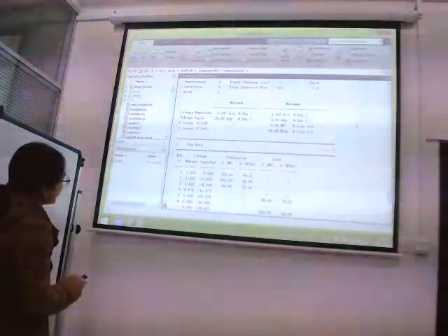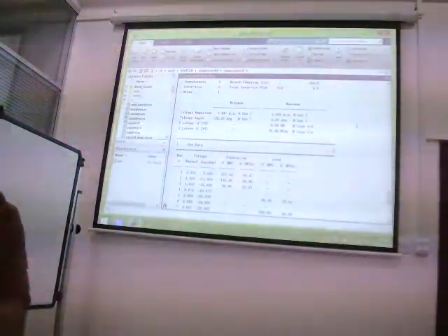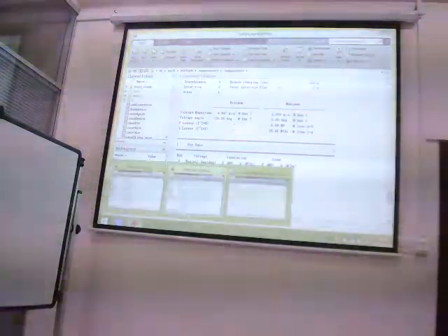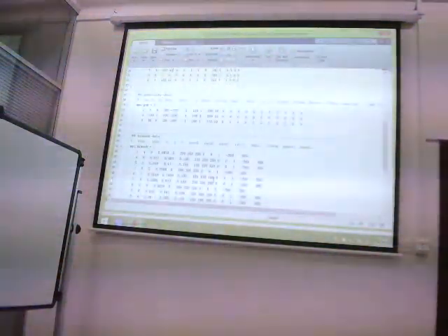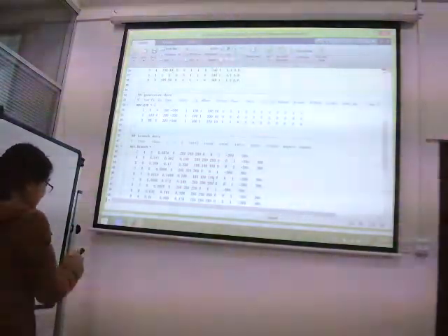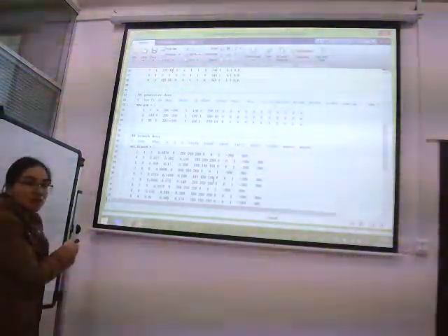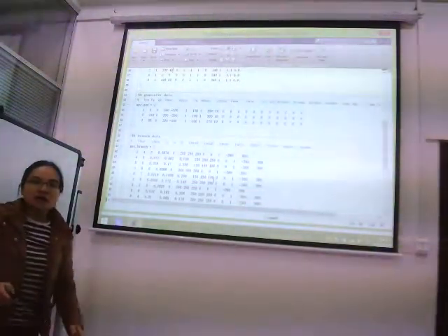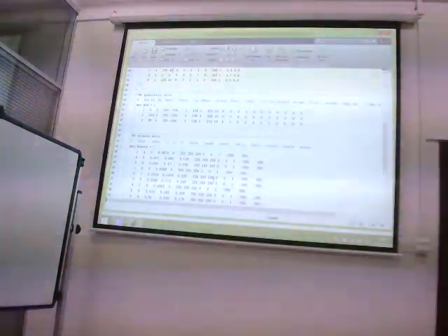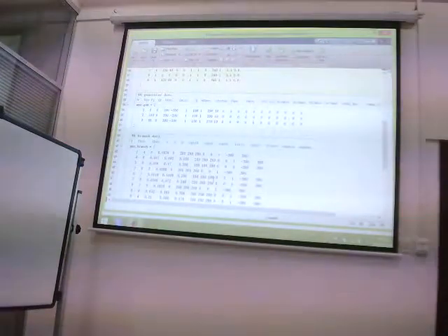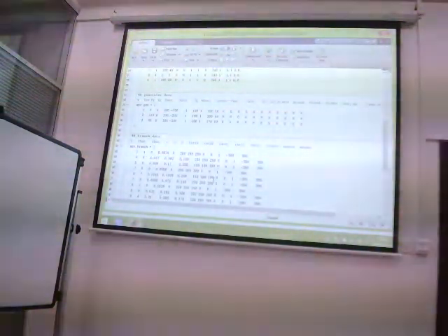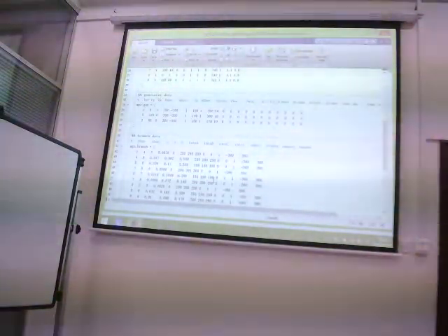Here is the generation, because the load demand is increased. For generator 2 and generator 3, the maximum generation values are 163 and 84 megawatts. If the load demand is increased, we can only use generator 1 to generate more power, because generator 2 and generator 3 cannot provide excess power.